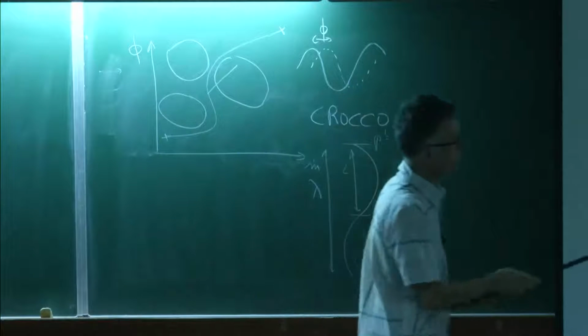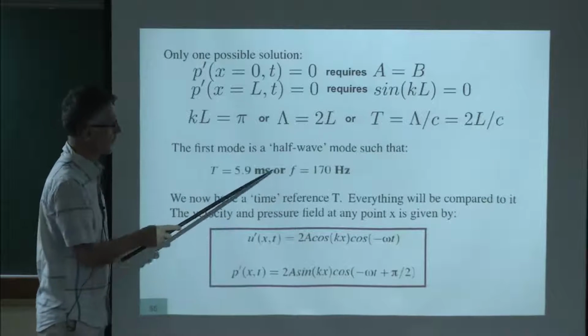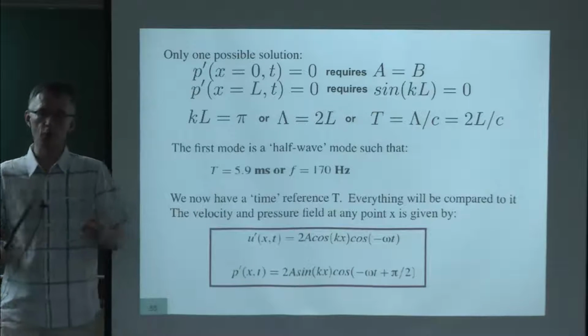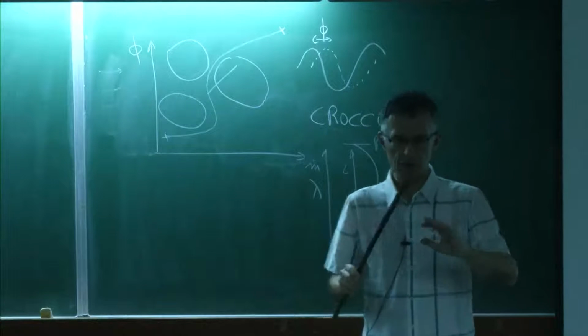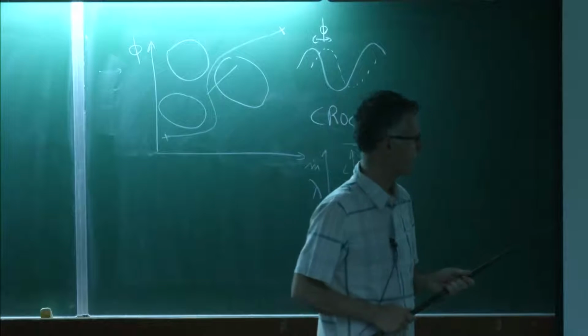And once you know the wavelength, you can compute the frequency and the period, and you find a frequency of 170 hertz and a period of 6 milliseconds. And you have supposed, and it's almost true here, that the sound speed is constant. So it's a flame which doesn't generate a lot of heat.